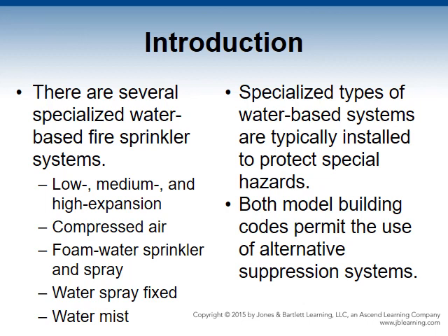They can be specialized water-based fire sprinkler systems, such as low, medium, and high expansion foam systems. They can also be compressed air foam systems, foam water sprinkler, and foam water spray systems. Also, it could be water spray fixed systems or water mist systems.